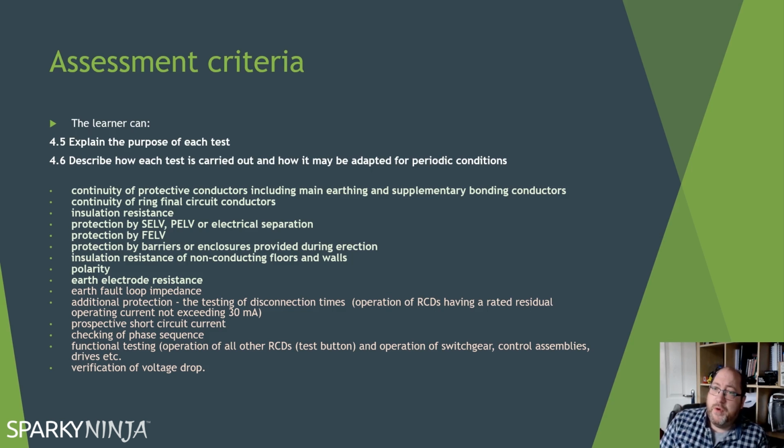Similarly with supplementary bonding conductors, the whole idea of the touch voltages, we need to verify the continuity of the main protective bonding and the continuity of the supplementary protective bonding, all to verify that the touch voltages do not exceed 50 volts.